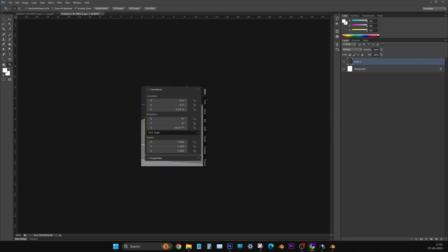So with this manual method only, we can create this spiral shape also. How? By rotating this empty. You just moved it now. Also just try to rotate it. Select the empty. Left in the viewport. The viewport selected. Yeah, selected. Go to the rotate option.